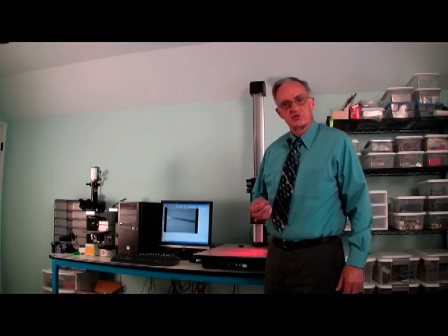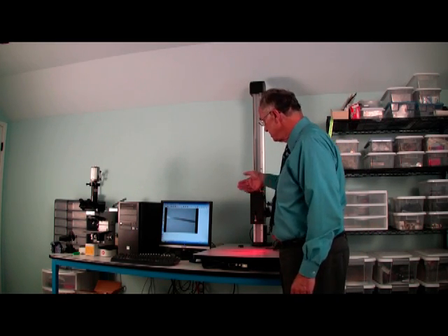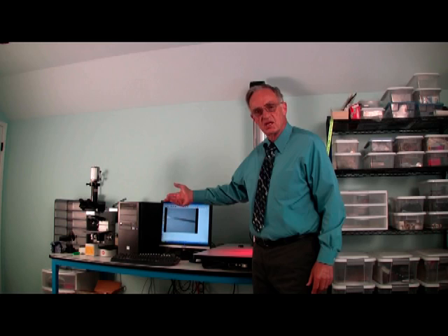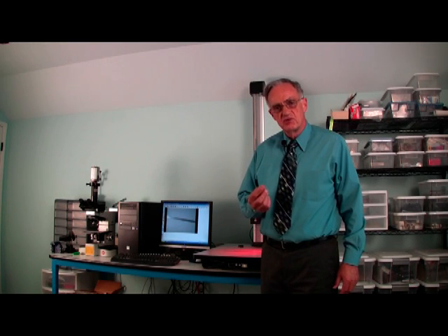Earlier, I did some work in the laboratory demonstrating some of the benchmark measurements. Let's go there now. Here we have a very simple demonstration system. It consists of a light source, a camera and lens, and a computer. After recording the settings of the vision system, the first thing we want to benchmark is the size of the field of view. I'll show you two ways to do that.